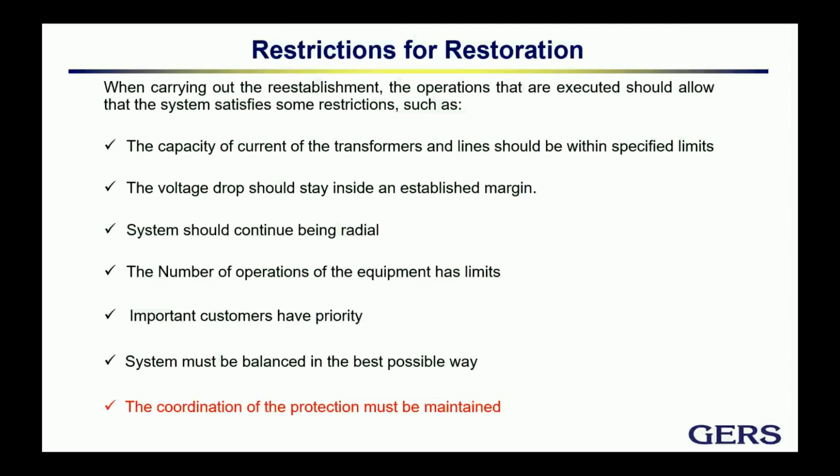The system should be kept radial. Still, we are talking about distribution systems, and they are not meant to work in rings. The other one, we don't want to have so many operations on the switching equipment. So the number of operations should be limited.